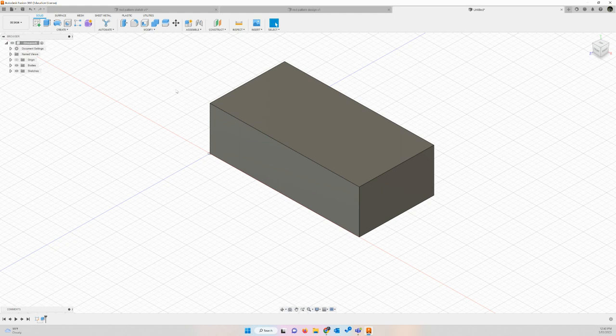And in this particular case, we're going to add a circle. We're going to position that circle. The circle will be a center diameter circle, 5 millimeters in diameter. We'll position it 4 millimeters from the top edge and 4 millimeters from the center of that circle, 4 millimeters from the left edge. We'll have our circle in place, then we'll pattern that circle. Finish our sketch, and we'll extrude and fillet all of our circles that we create in the pattern.